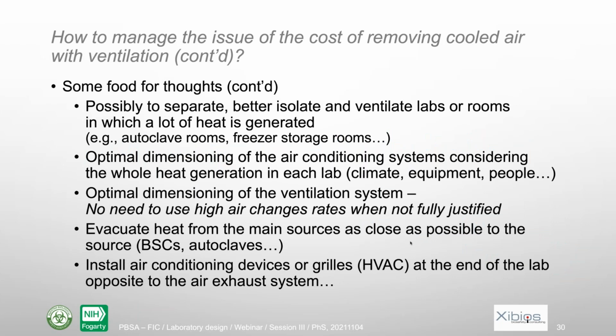Another consideration: you could possibly separate and better isolate and ventilate labs and rooms which need it the most, because a lot of heat is generated there. That means autoclave rooms and freezer storage rooms. Those should be separated from the labs, better isolated, and also very well ventilated. Also, you should define the size of the air conditioning systems. This is true for HVAC, but also for the fans. And that should be calculated considering the heat generation in each lab.